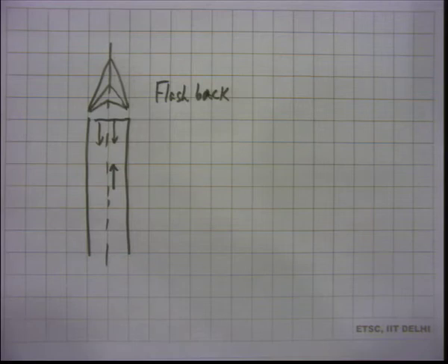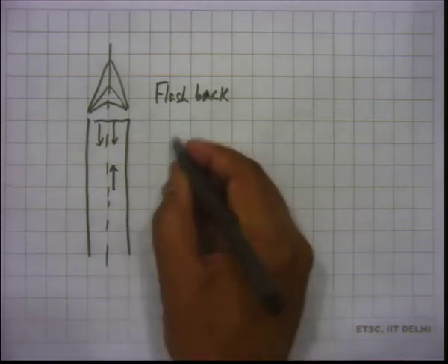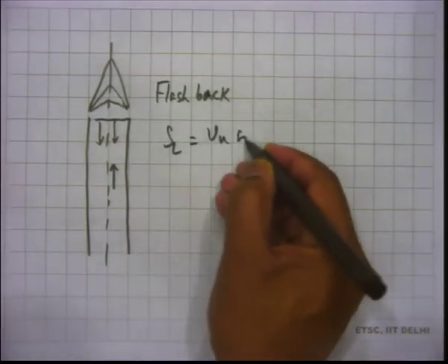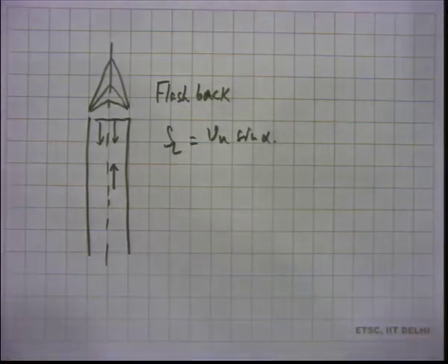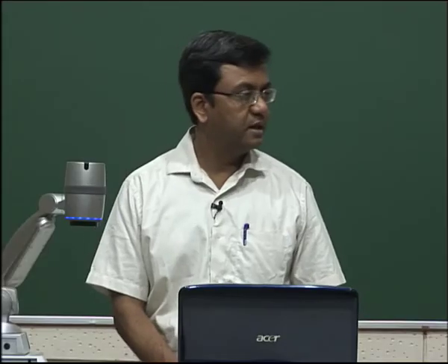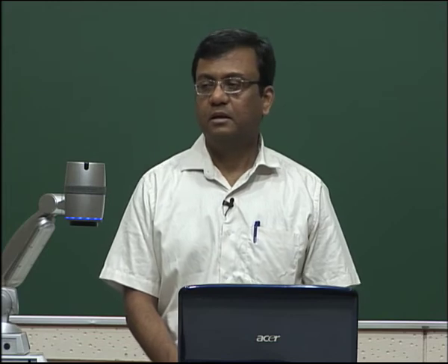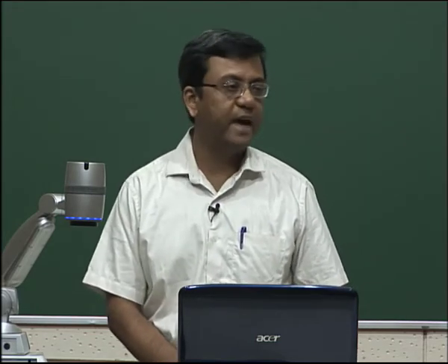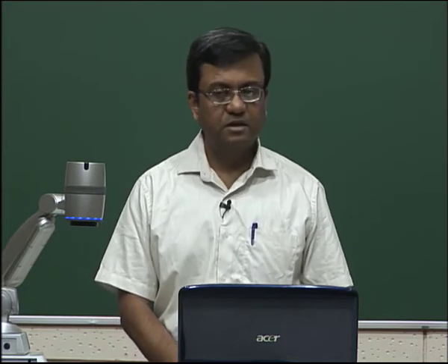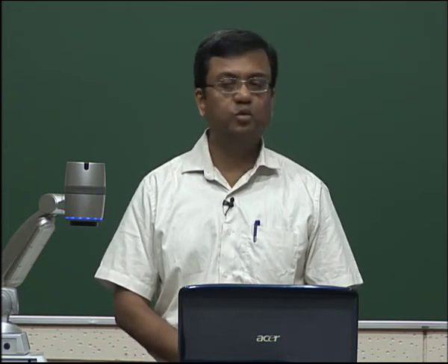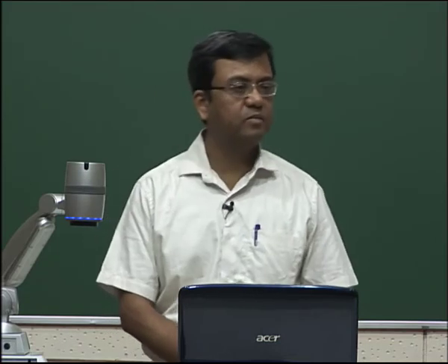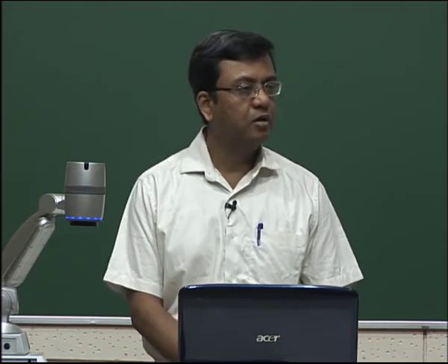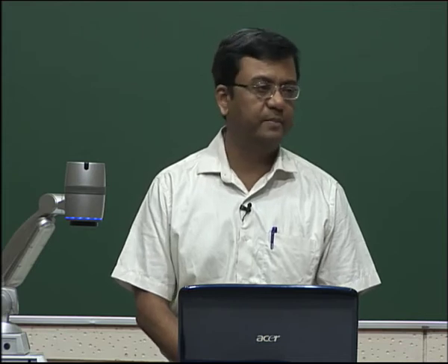SL is small compared to the laminar burning velocity. So, we are looking at this balance, right? SL equals Vu sin alpha. If we keep on decreasing Vu, a point will come where Vu is smaller than SL, and then the flame in that mixture will tend to move back into the burner, because the flame, to be able to remain in an anchored position in the form of this cone, requires a certain feed of fuel air mixture.